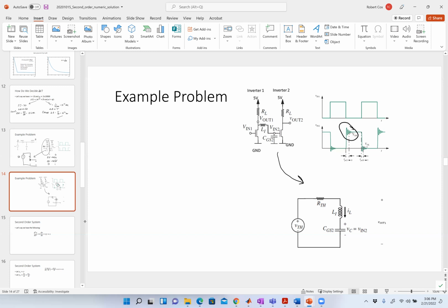More resistance, okay? If I made my R get bigger, then that would get smaller. Now, everything in life, everything in design has a trade-off. So if my R gets bigger, that underdampedness goes away, but what happens as a result of that R? There's going to be losses that come with it because R means losses. It also is going to make the transient get slower.